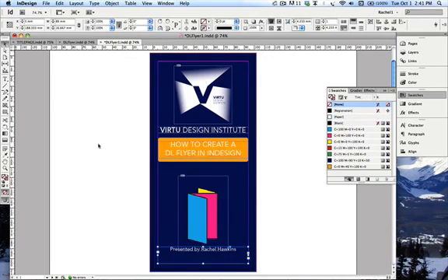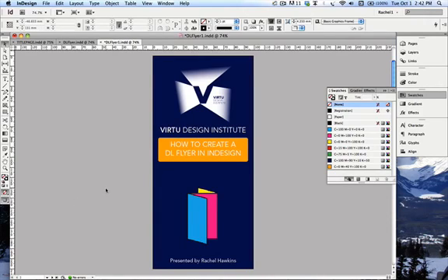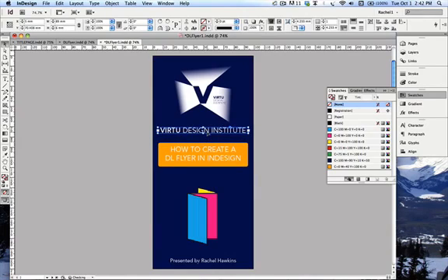Now, the only other thing to note is see how it's sitting at the top of that box. I've got two things I can do. I can either drag the box down so it sits down where I need to on the baseline of the flyer, or I can go up here and adjust where the text aligns to within the box. I can go to the middle of the box, the bottom of the box, or the top of the box. And in this instance, I'm going to go the bottom of the box. Nice and easy, a little adjustment, and we're looking good. That's pretty much the whole front of the flyer. So we just select things and you can jig them around until visually it looks like you want it to.